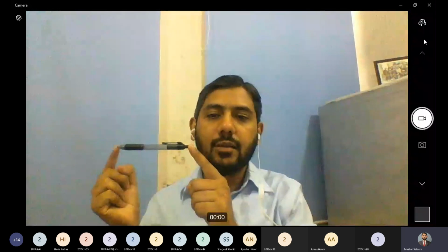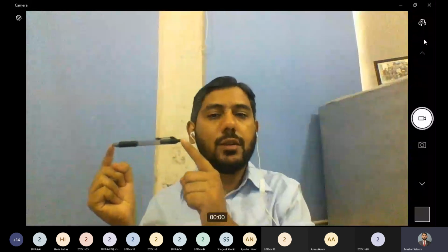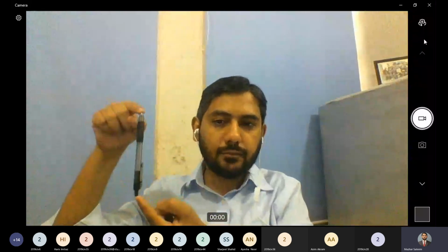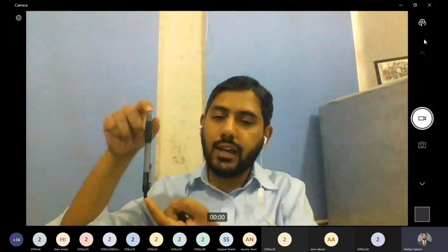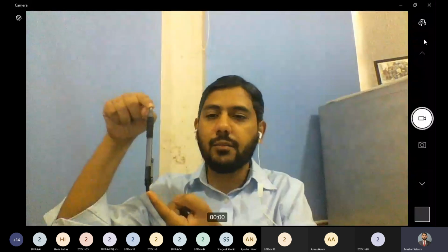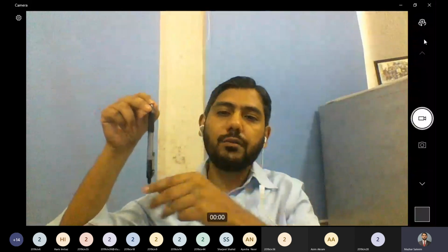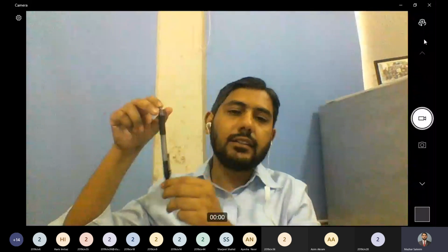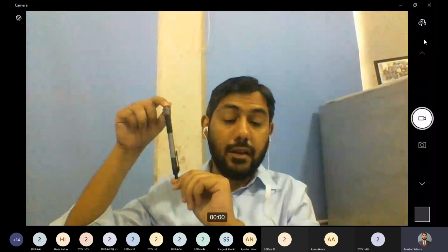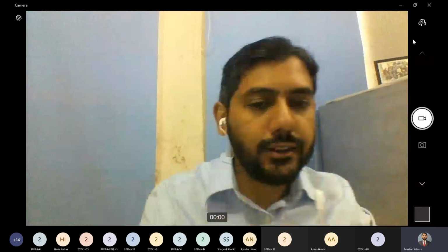So when we design this member, we will design it as a column, although it is horizontal. Although in most cases beams are horizontal and columns are vertical, that is not an absolute truth. We can have inclined or vertical beams. If we have a vertical member and the load is acting transverse to the longitudinal axis, then the behavior of this vertical member will be like a beam. It will bend like this, out of plane, and it will be analyzed and designed like a beam. So the nature of loading is important while defining the behavior of any member.